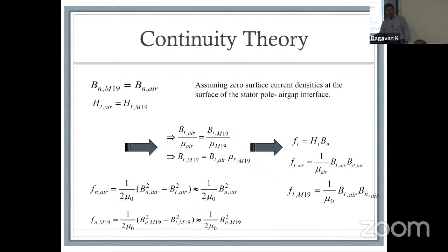You can create a simple equation. The way your magnetic flux inside the electric machine is broken down, it gives you typically N and T. When you're doing this calculation, you might need to decompose your fluxes into XY components and then reconstruct back to make sure you have the right components when you add. Keep in mind, when you're adding them together, they have to be in the same direction. If they're not in the same direction, by definition, normal forces cannot be added because they are all at different angles. You can add the tangential components because they're all in the same direction, plus or minus. They are going along the tangential direction, but the normal components cannot directly be added.